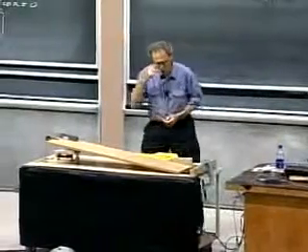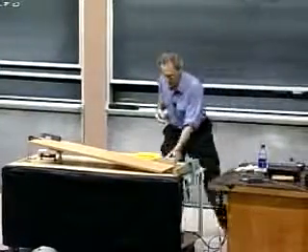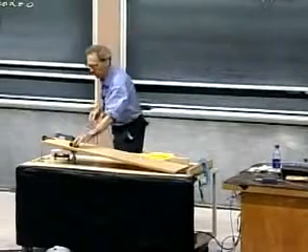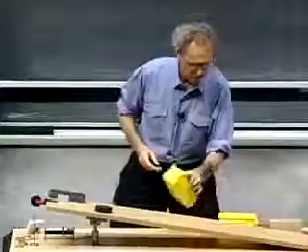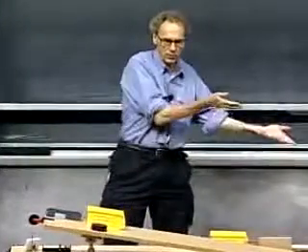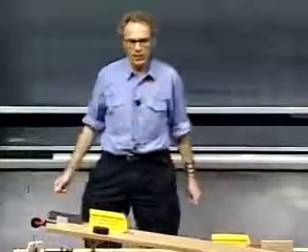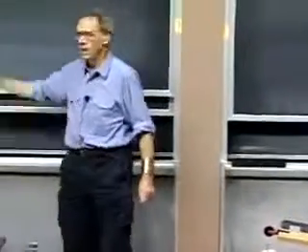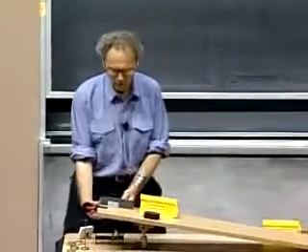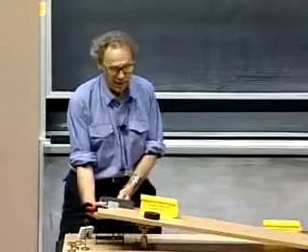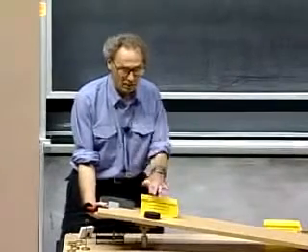The first thing I want to show you: I take a rubber puck and put it on this incline, and I have a plastic bin, which is quite smooth. It's immediately intuitive that the friction coefficient of this plastic bin will be lower than that of the rubber puck. So when I increase the angle, you expect that first the plastic bin will start to slide and then the rubber puck. If I gave you the angles at which that happened, you could calculate the two friction coefficients, which I will do later. All I want you to see is that this one will go earlier than that one.